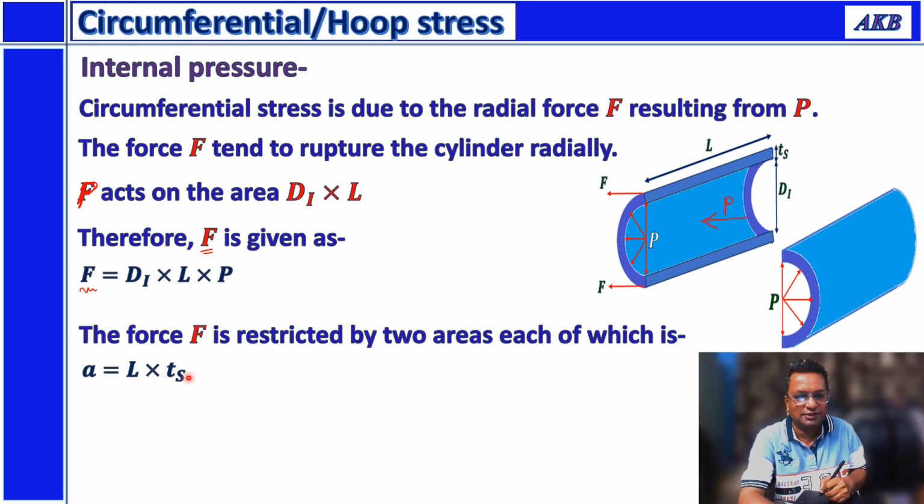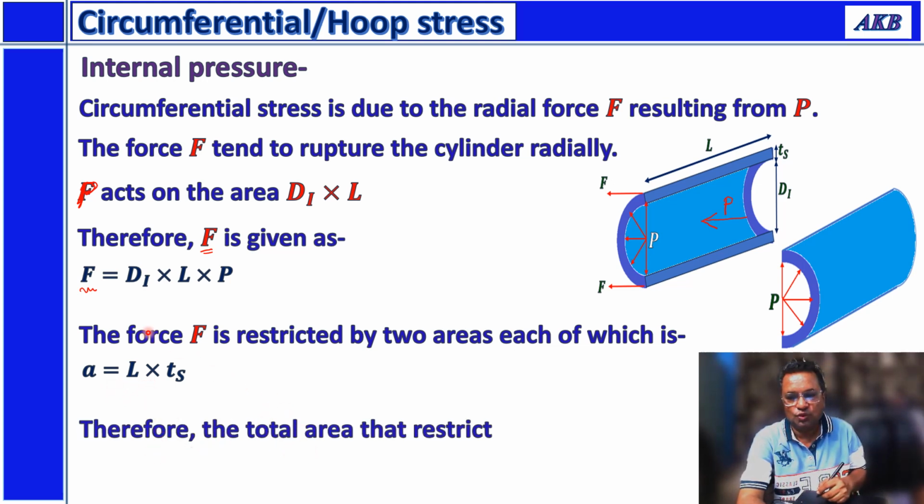There are two areas that will be resisting the pressure force F, and each is given as L into Ts. If you know the force and the area on which the force is acting, you can easily calculate the stress.